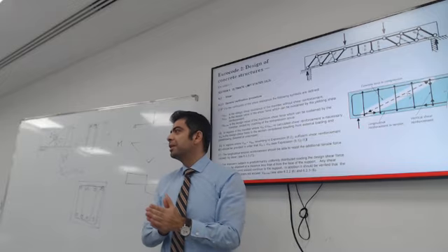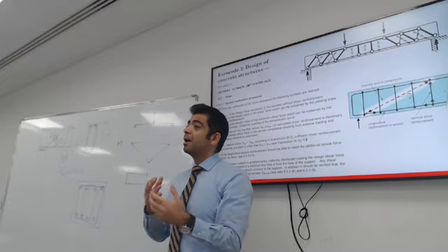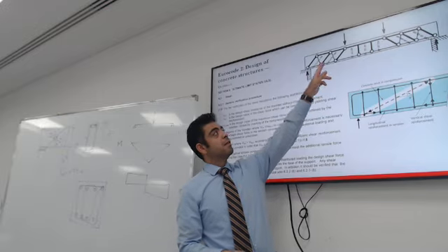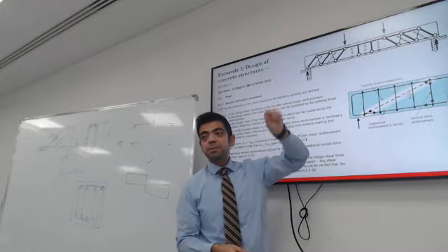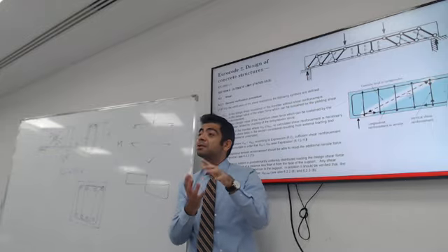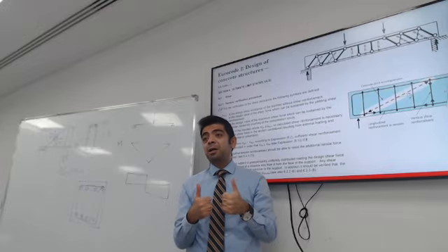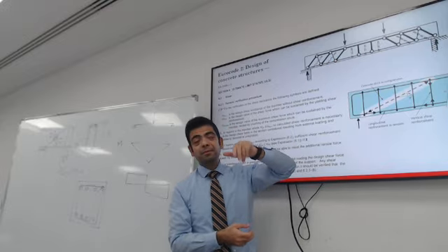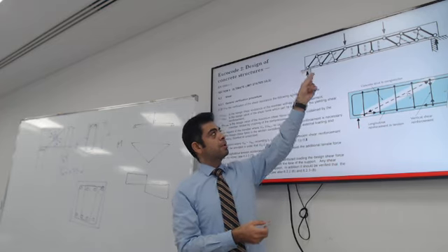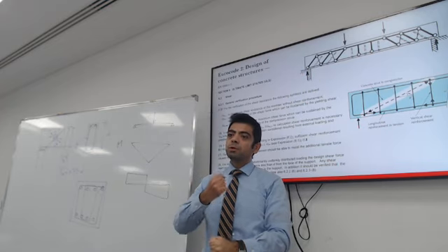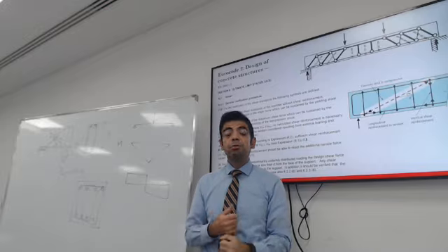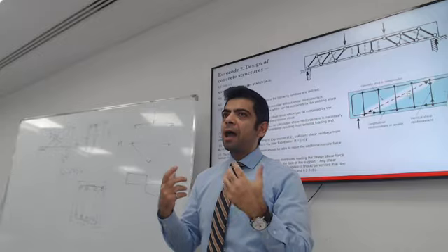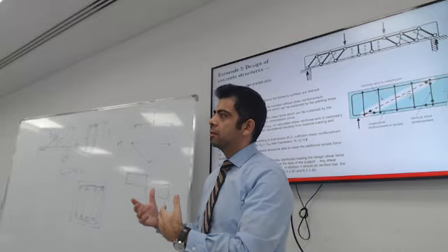It's almost as if the load in the beam is trying to work its way in a truss like this. The black wide strips, this is compression, and it's resisted by concrete. Concrete is very good in compression, so it can resist the wide black members. The thin diagonal members, these are the stirrups. They will resolve the load in tension. It's a pretty good assumption to analyze how shear is going to work its way to the support.